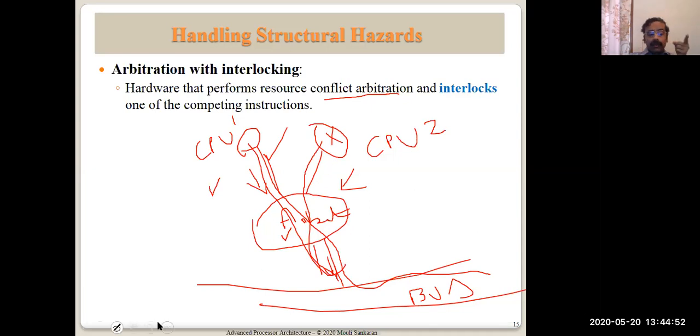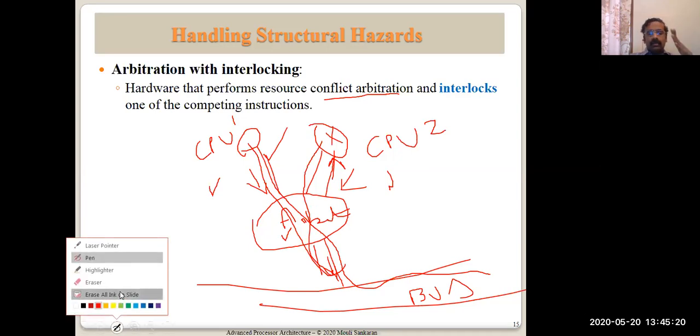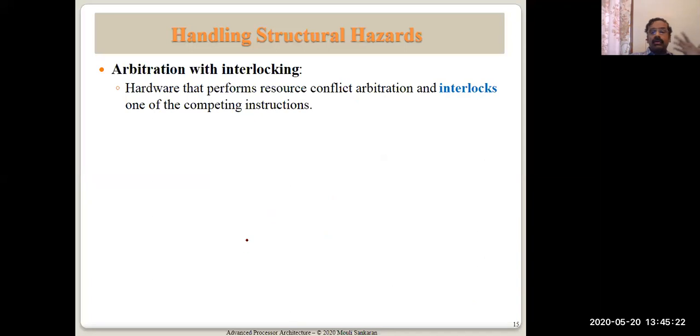If you remember, the CPU memory interface always has a wait signal coming from the outside world. So when the wait signal happens, the CPU stops. It stops the cycle. It doesn't go further at all. It is like a frozen CPU. So until the bus is released, the CPU stops, and then it will start again. Okay, this is how different hardware implementations are. You have to read on your own. Quite a lot of things are there to read on your own to learn.